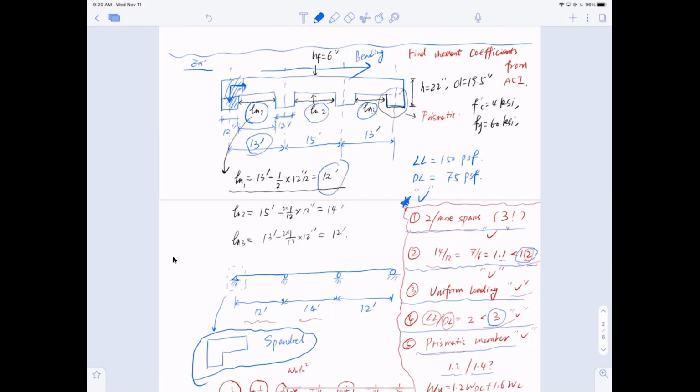You run a check. And we will most likely give you the dead load and live load. And people still ask the question, look, Bob, if you say the self-weight has to be considered, what do you mean by that? Like I said, you just use the height, which is hf, 6 inches, multiplied by 150 pounds per cubic foot. And that gives you the self-weight of the slab.